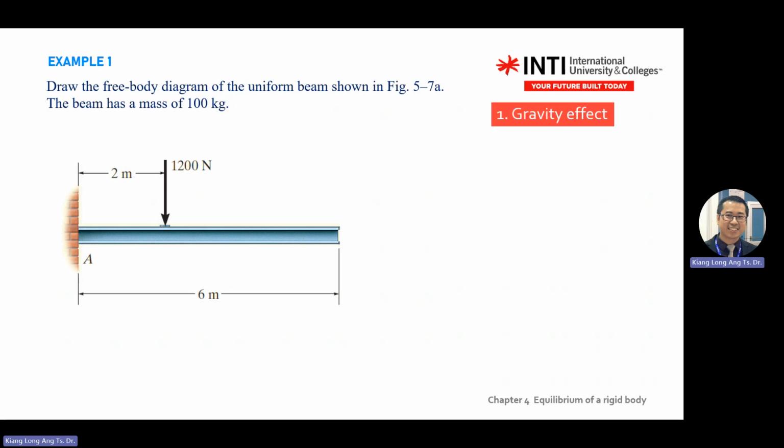So see if you're able to see. Okay, some of you already forgot this point in the first steps. Remember W, remember W in your answer. Without W, your solution for all the force equals 0, all the moment equals 0 will be wrong. So if you start from the free body diagram and draw it wrong, your answer for the analysis is wrong already.